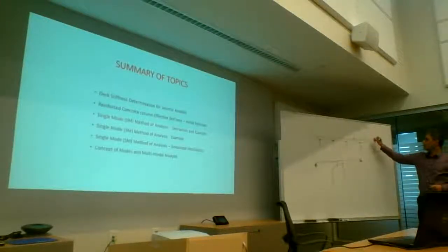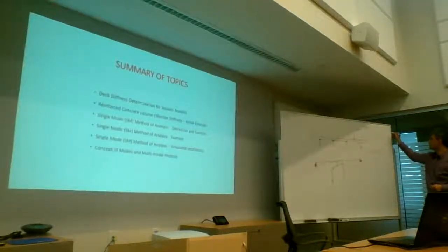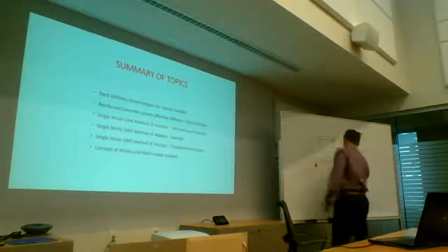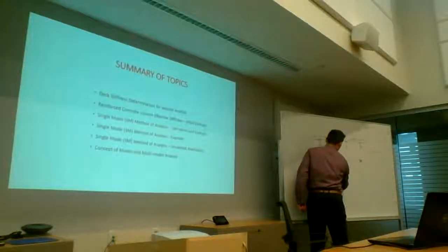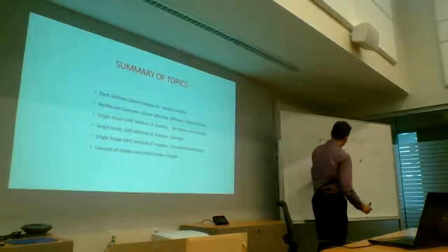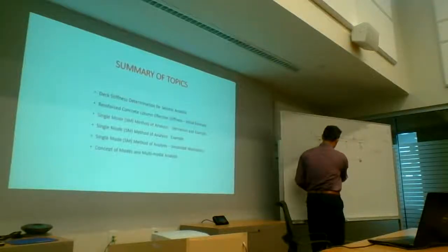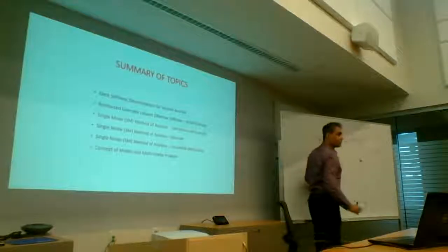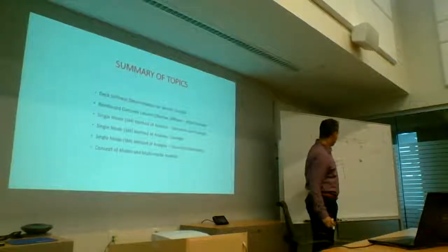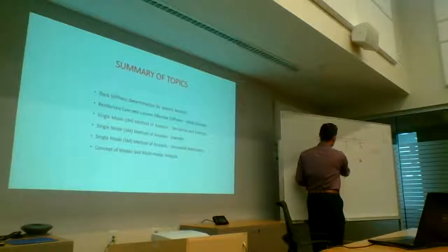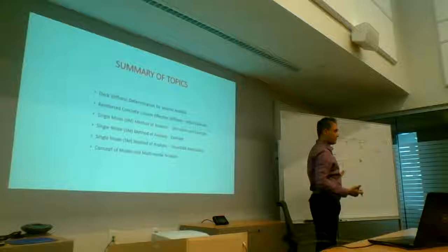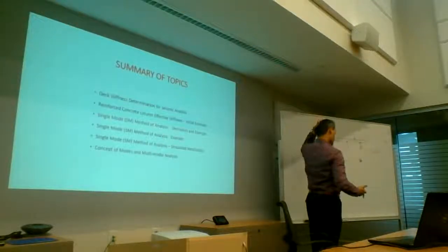So what I want to talk about is how do we come up with the vertical stiffness of this, the transverse stiffness of this, the area, and then the CG. The CG helps us come up with the height of that element, which puts the CG of the deck at the right location. Because imagine if your load is being generated here, it has a certain lever arm to your foundations. If it's generated higher, then if you model it lower, you're going to have a bit of a discrepancy. You're not going to be able to capture it appropriately.